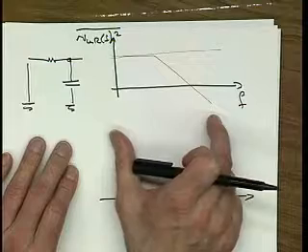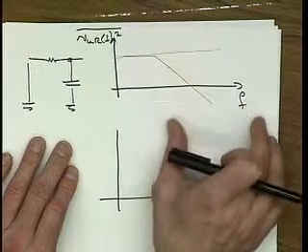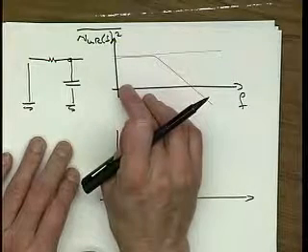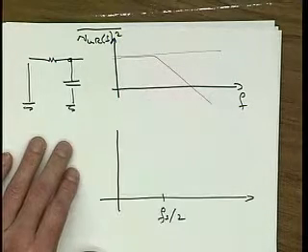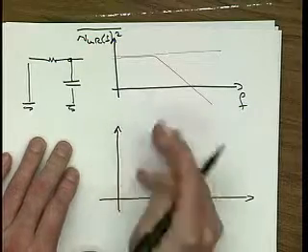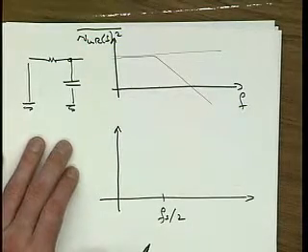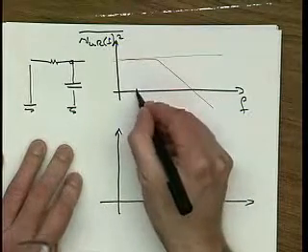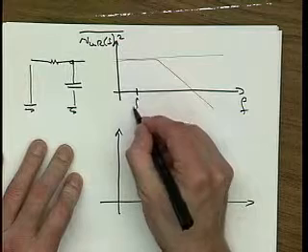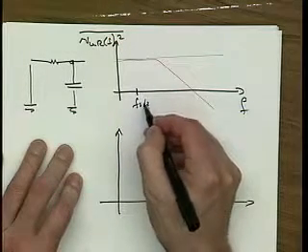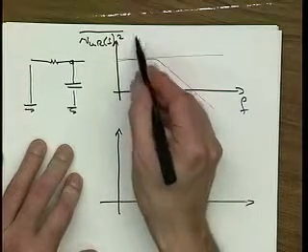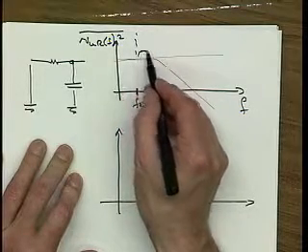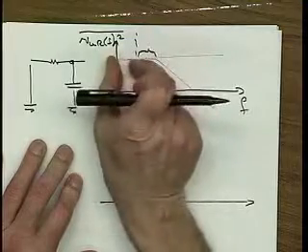And because of the sampling, all of the noise that was at high frequencies here folded down to lower frequency. Well, so what the spectrum here is going to look like depends on the sampling frequency. If we sample somewhere like here, well, I made this already, fs/2, then that means we retain what we had already, and we take this one, we flip it around and put it on top here.